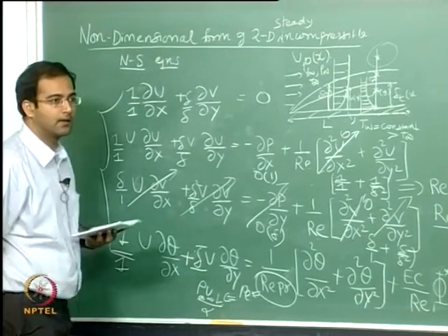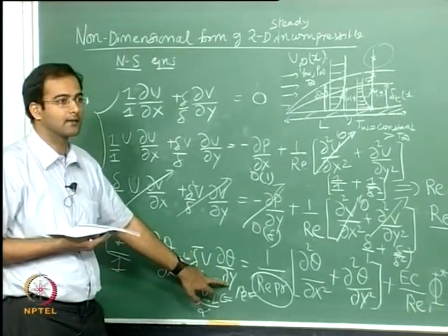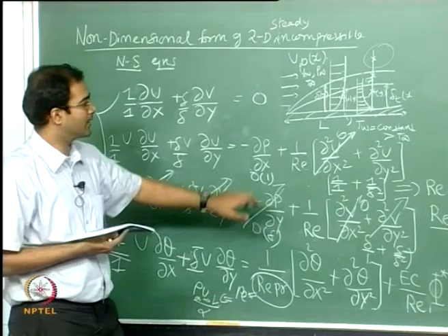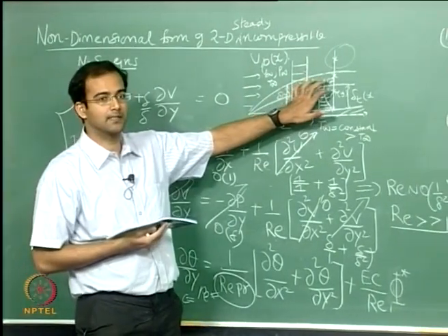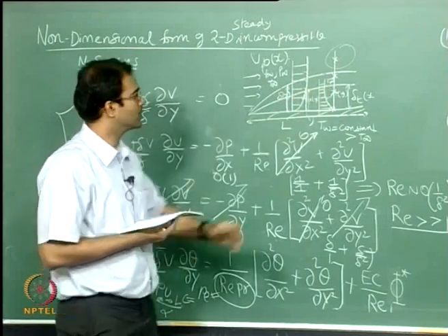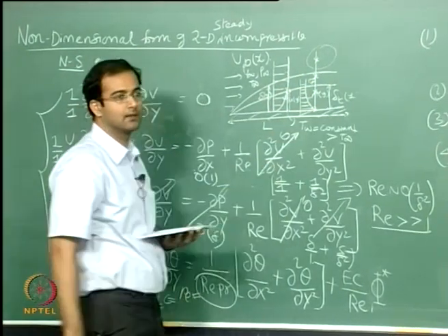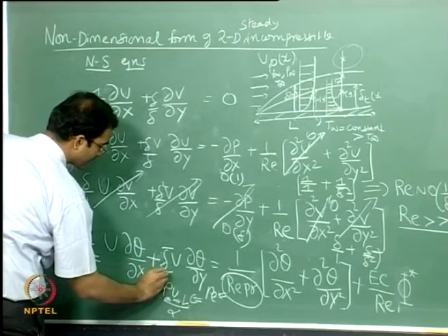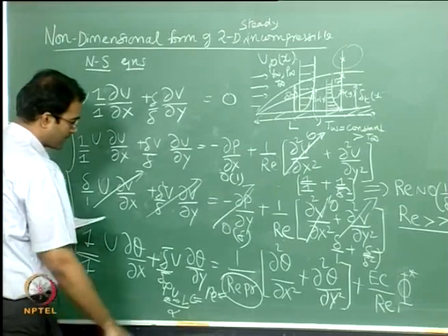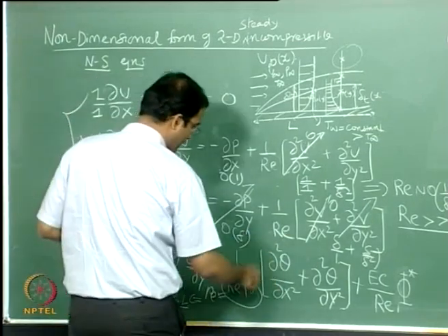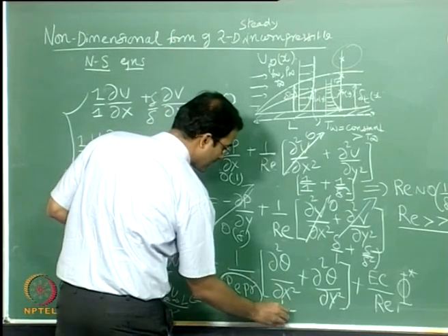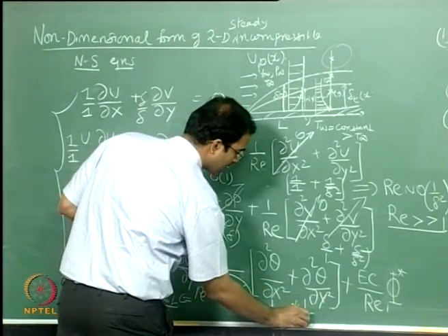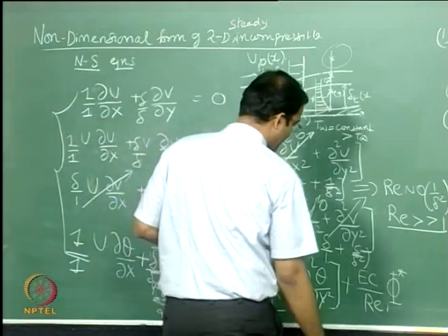Now, when we are considering the temperature gradient, which boundary layer do we have to look at? The thermal boundary layer. So for temperature gradients in the thermal boundary layer our y scales with delta T, therefore we have to use this as the scaling parameter. So we will say that this goes as delta T bar. Coming to this term right here, this is of the order of 1 plus 1 by delta T square. I do not have space, I am just squeezing it in.